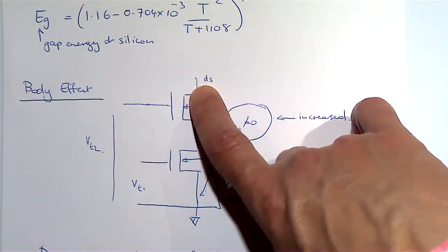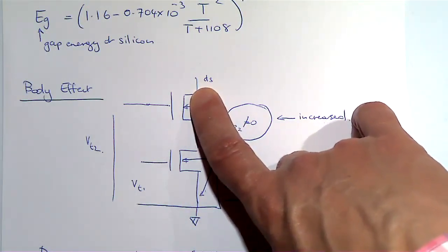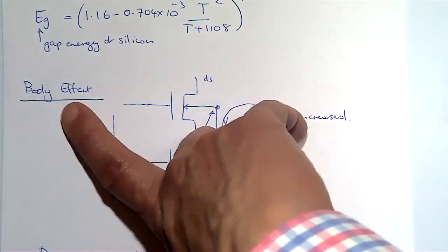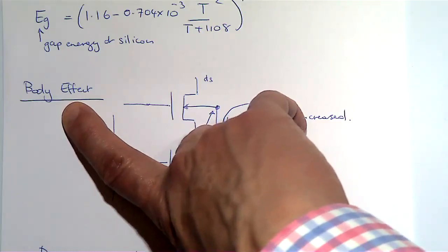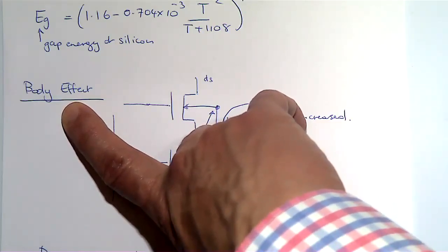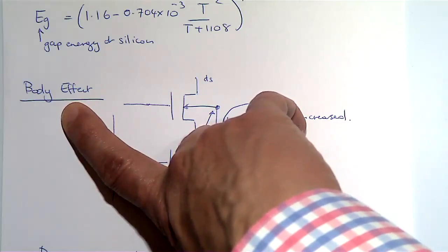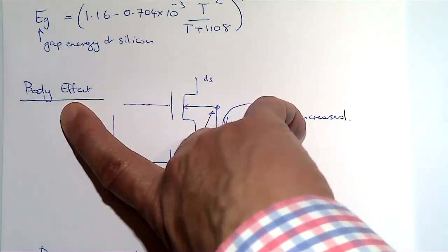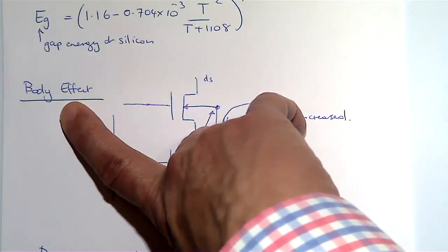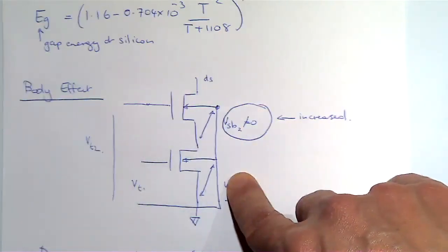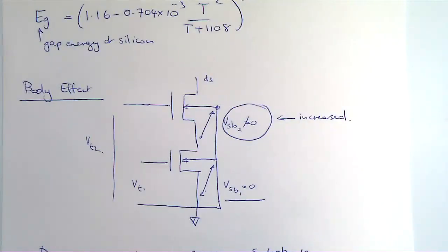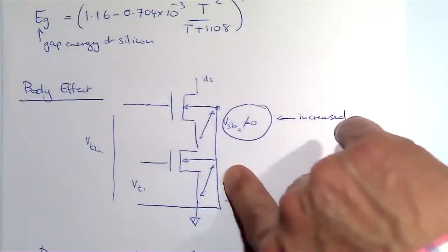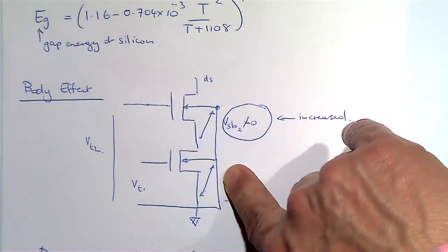But if you add 3 or 4 transistors, the issue is body effect starts becoming more and more predominant, and as a consequence of that, your threshold voltage changes, and after a while you can't do that anymore, right? You don't get any more gain in doing this, or actually setting it up in this particular configuration. And the other reason why I wanted to bring this up was also, other than for logic circuits, this is one of the tricks that you can also use if you're trying to build, for example, power amplifiers, right?